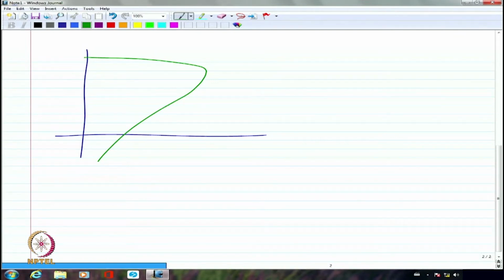Actual speed torque characteristics will be somewhat like this as far as the induction motor is concerned. This is definitely not a linear region, whereas this is the linear region, and this is going to be slip equal to 1, this is slip equal to 0, this is going to be omega r equal to omega s, this is omega r equal to 0. Omega is increasing in this direction. Right? And this is TE. So this is the typical speed torque characteristics of a three-phase induction motor.